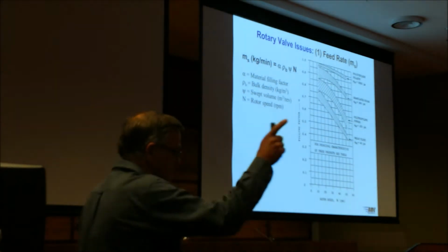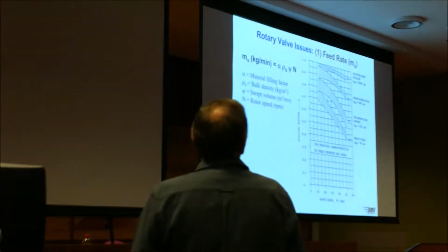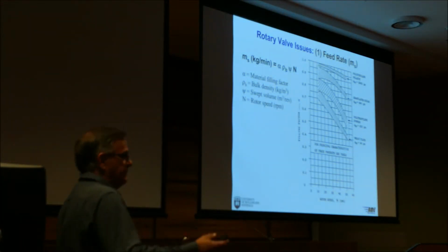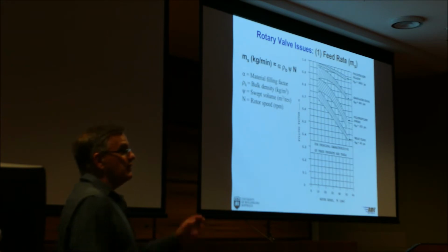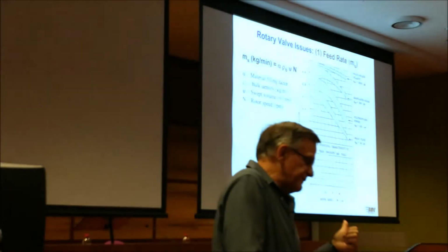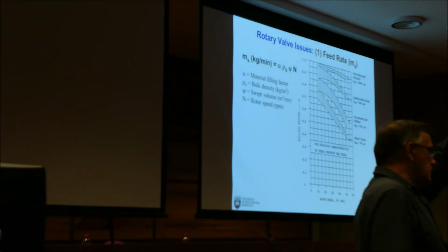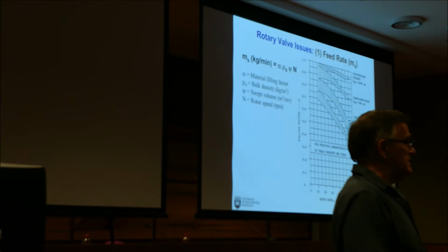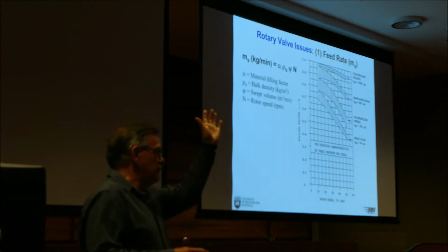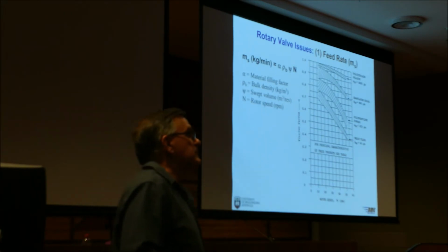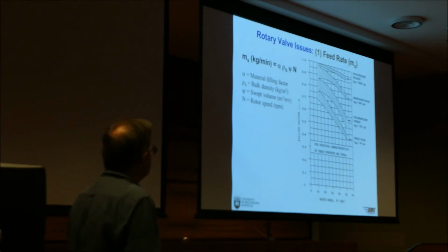But strictly it's based on the distribution and then where your 50% value is. Then you can work out other things like standard deviation, but with particle size distribution we don't do that. The main parameter we use is D50, the other ones are D10 and D90. That's where the 10% value is, what the particle size is, and the 90% value. This gives you some indication of the spread of particle size, roughly where the minimum is, the maximum, and the midpoint. I'd rather use the whole distribution, it makes it easier.